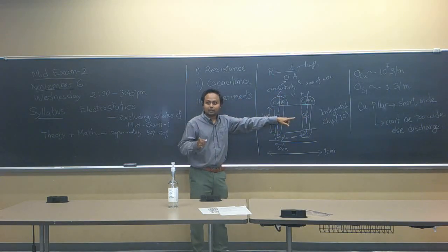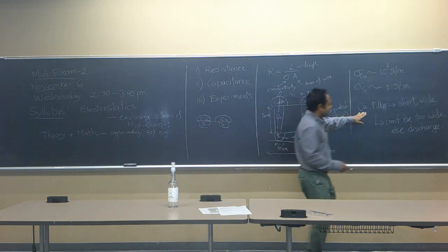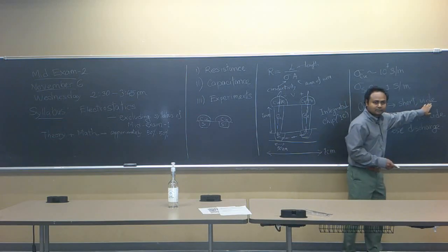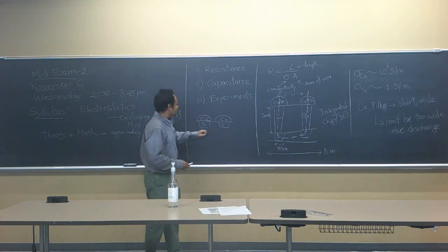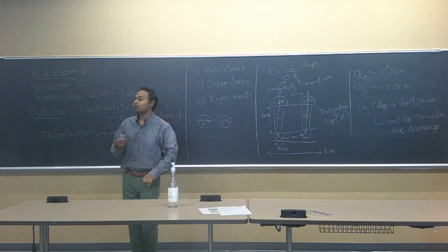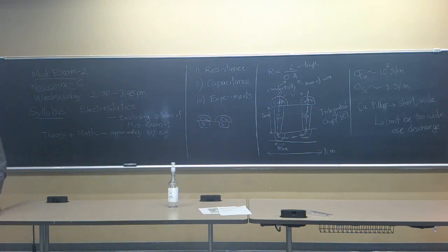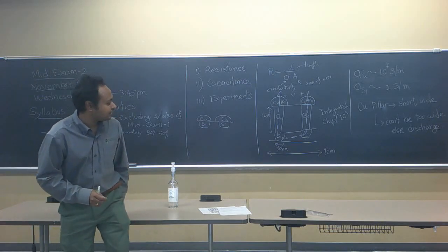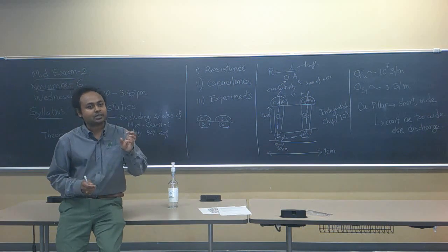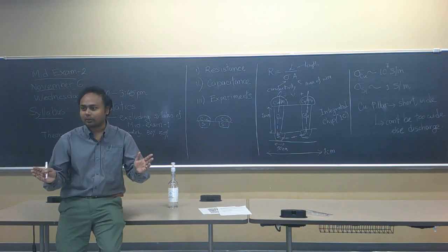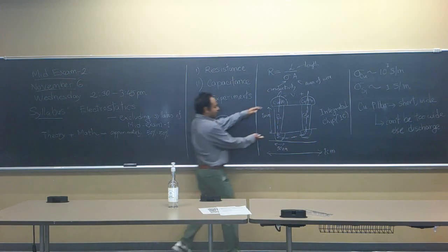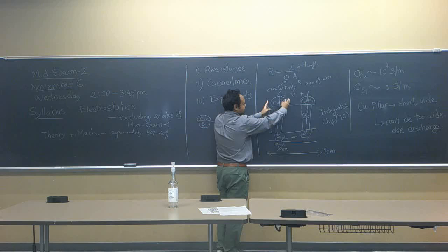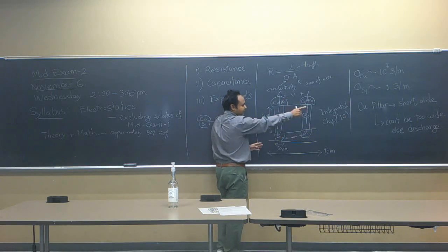You see it? More resistance, right? This is more resistance. So you have to make it wide. If you make it very small, your resistance is going to go up, right? And also, remember that if you make it very small, they are more likely to fail. So failure is one thing which you need to take care of, that you cannot make things arbitrarily small, and you cannot make things arbitrarily small because the resistance is also going to go up. So two things. One, your copper pillar cannot be arbitrarily short, otherwise this size has to be reduced down, which makes a problem, resistance goes up.